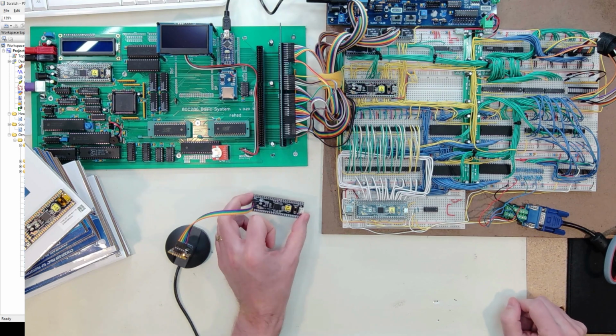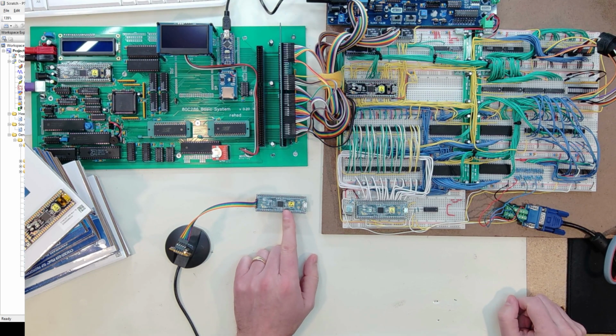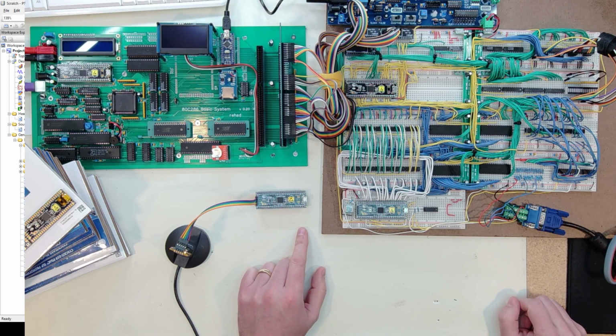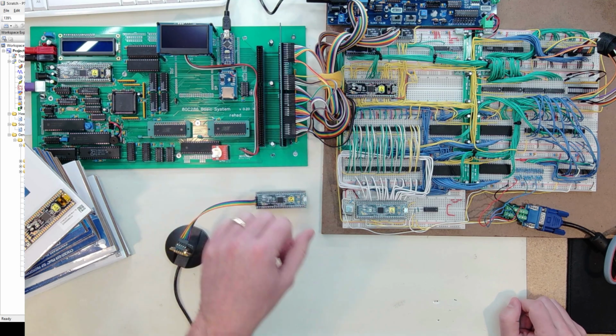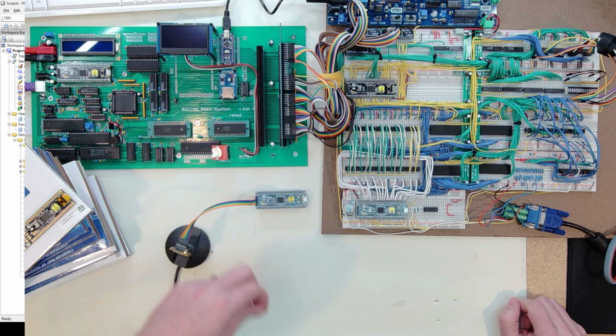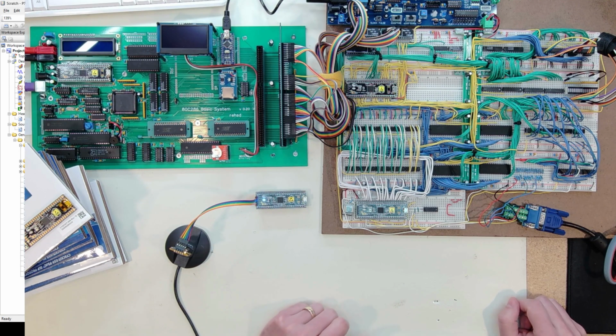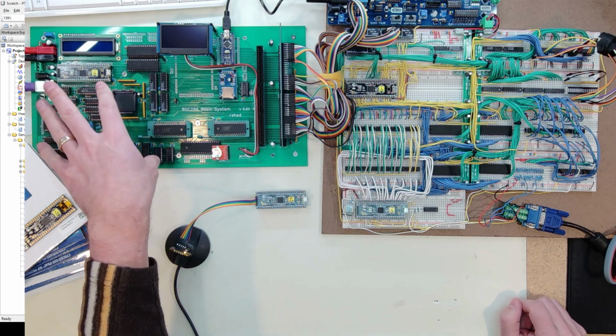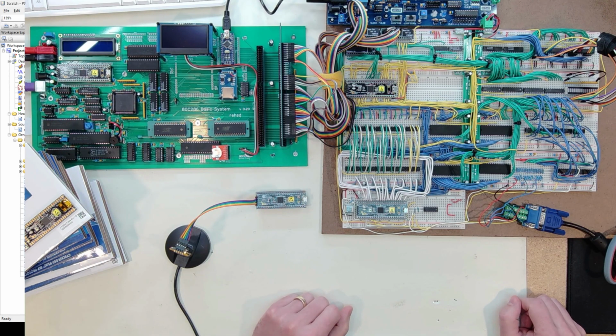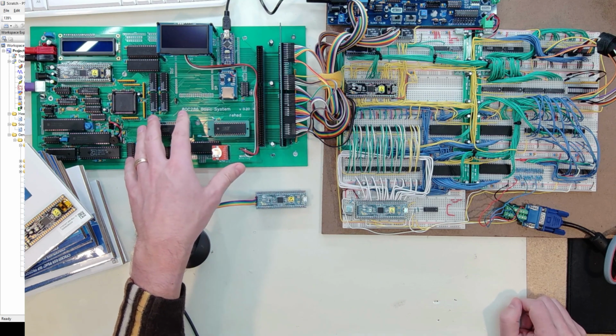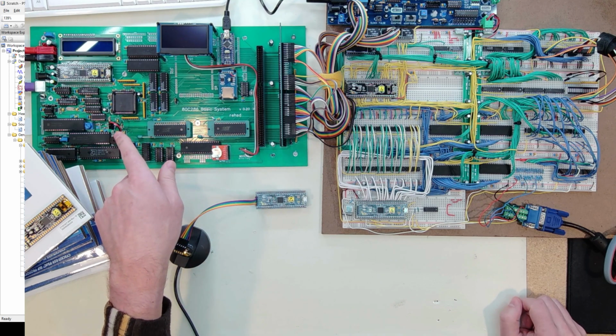So for me, these little devices at $15, even in some of those cases like the VGA logic, for me to go in and grab 22 different chips, I'm going to spend as much money on those chips as I am on this little PSoC, if I can get my hands on these PSoCs at regular manufacturer price. Now, maybe in some of my designs, you would say I'm kind of cheating. Back in a 286 system, you wouldn't have had a PSoC back in that era to work with. And yeah, that's true. So could I break this out into separate ICs? Yeah, I definitely could. But my goal with the 286 build is not to do basic address decoding. I kind of have a good feel for how to do that.